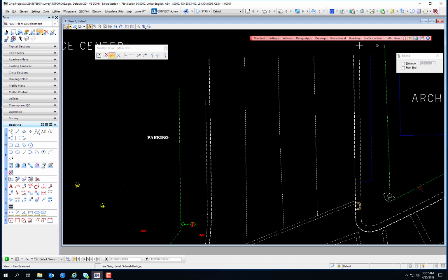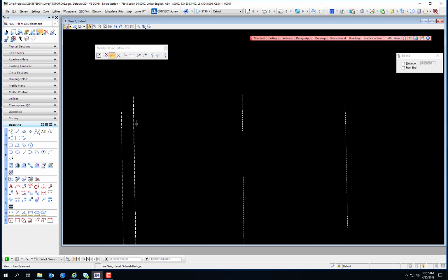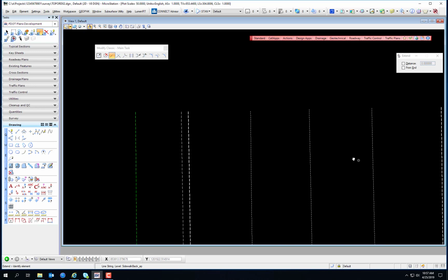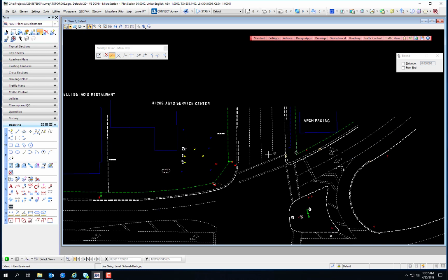Now, for example, if you extend one too far, you can still use the Extend Line tool to reduce the length of that line just by snapping. See that green line? Snap to that line. So the Extend tool works both ways. Oh, that one's, yeah. The line style of these, the little dashed line and the angle that it's at makes it look like they're not lined up, but I believe those are all lined up correctly now. So that is the Extend Line tool.